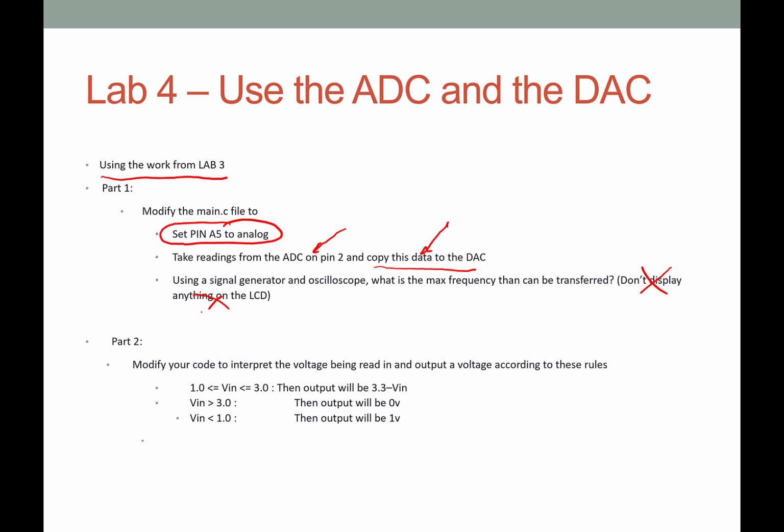help you, but don't decide that you're going to use something like 20 megahertz to start out as your frequency. Do something low, super slow, 10 hertz, 15 hertz, 20 hertz, just to make sure you're doing things right. That's one of the things that I think you have to start grasping with, is now that you're getting into circuits lab and you're starting to do things more on your own, and you'll see this in electronics lab for sure, you have to make decisions about how you're going to test something.